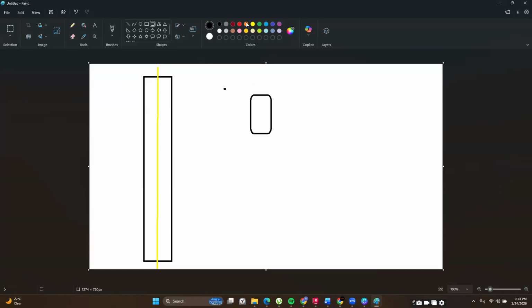So you have these axes. We said for these members, you have the major axis going in this direction, and then you also have the minor axis going in this direction. So in Robot, the major axis, or the axis along the deeper section, is always Z. This is the local axis system for Robot.